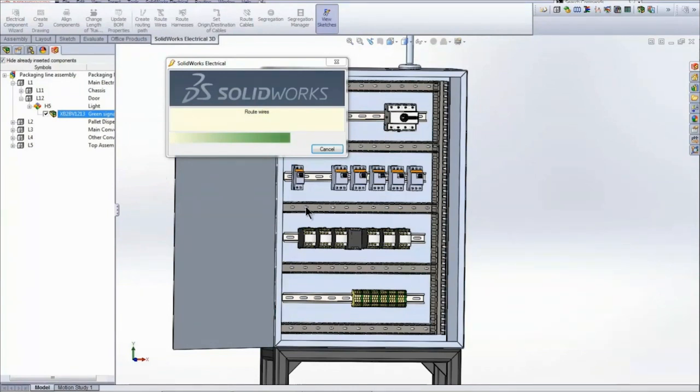If, for example, you specified in the schematic that the wire should have a fixed length, you'll either get an error to tell you that the system cannot create the route for that wire because of the fixed length, or it'll create it, but it will go through components and give you undesirable results.